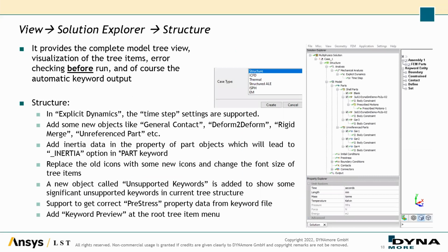The developers also improve the solution explorer more and more. The solution explorer is to create LS-DYNA input tags in an easier way, and it shows what you really have to define to have a successful LS-DYNA simulation at the end. So it provides a complete model tree view, visualization of the tree items, error checking before run, and of course the automatic keyword output. And you have to select between different case types of LS-DYNA: structure, ICFD, turbo, or electromagnetics.